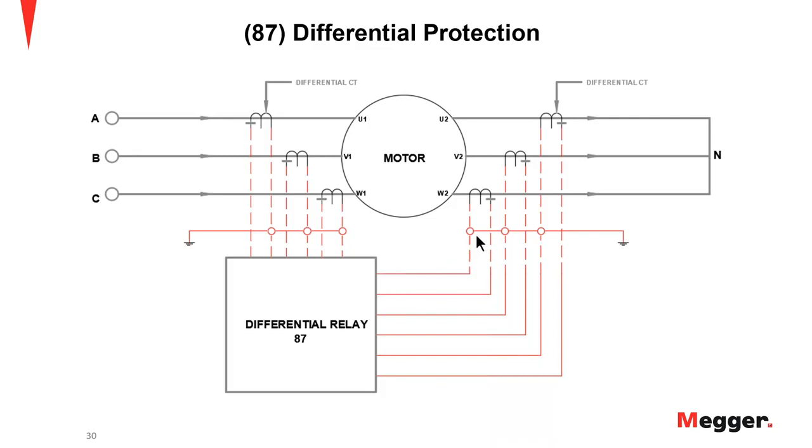Now, it is good to have these grounds at the relay, where you have one grounding point for your CT circuit inside the control house. But sometimes you don't have access to a lot of these different grounding points. So sometimes you have to ground it outside in the marshalling cabinet, which could be outside in the yard, or in a pass-through, or in a vault underground, however that happens. So really, as long as you don't have two grounds on the same current circuit, you're okay.